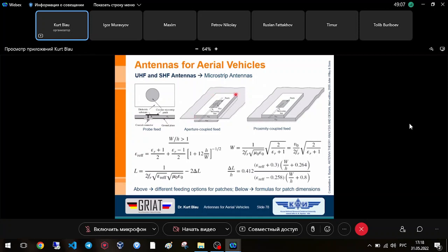It's the radiating patch, and the microstrip line goes under. This is the ground plane for the patch. And here in the ground plane, in this plane here, a rectangular window is etched, and so the strip through the rectangular window is coupled to the patch, which you can see on the surface.